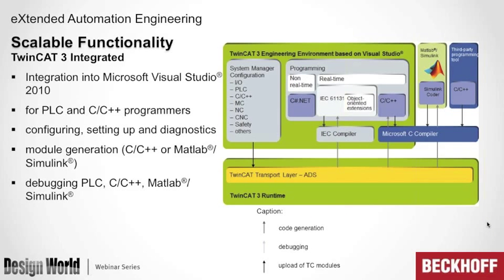Now, if you are a Visual Studio user, great. TwinCAT basically is a type of project that you open up, and you can have everything else there at the same time. And again, one debug environment, which if anybody's done much programming, is a very handy thing when you're working on an HMI and also working on a control program. Sometimes it's a chicken and egg thing. What's causing a problem? To have one debug environment greatly simplifies the creation of code.